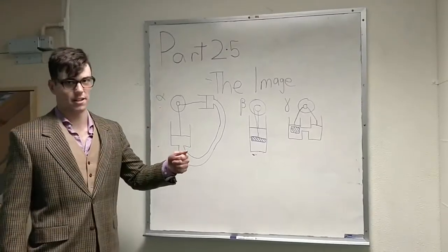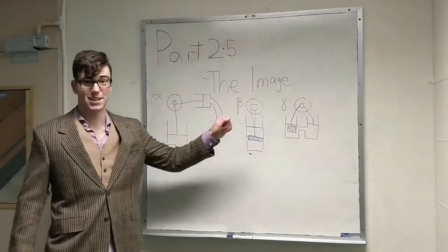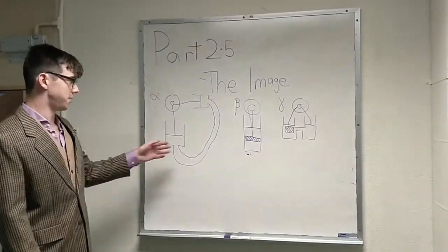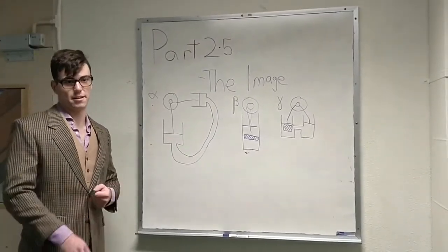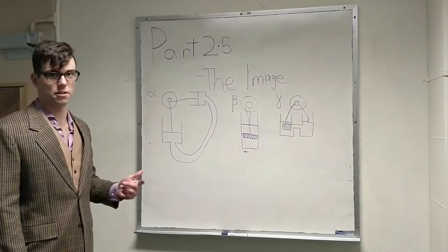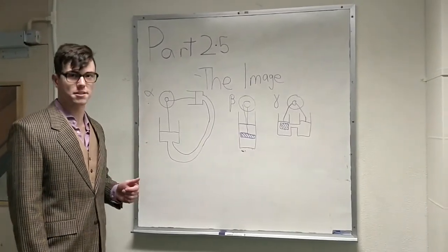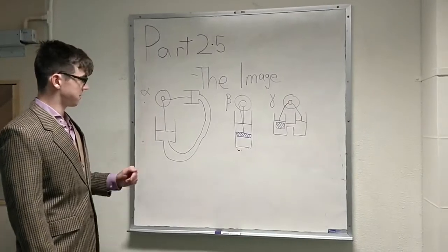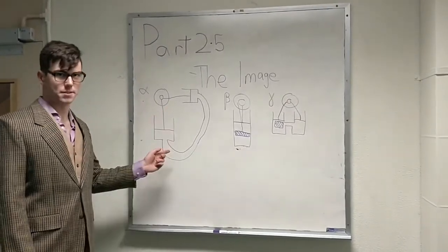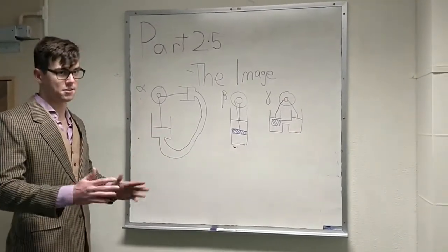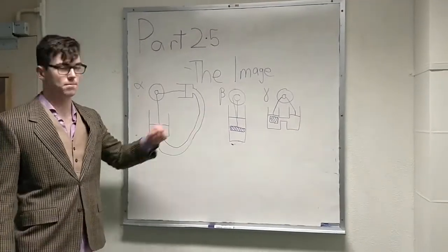There are three types of Stirling engine: alpha, beta and gamma. Each of these operate by compression and expansion of hot and cold gases, however they do so in slightly different mechanisms. The alpha type Stirling engine has two separate pistons, totally separate, and they just act on each other through a tube between the two of them.